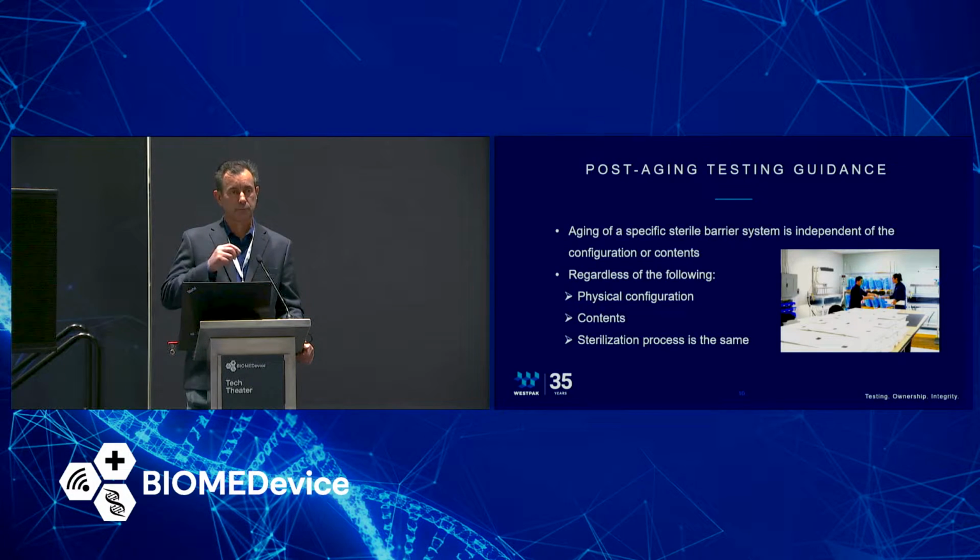And the aging, if we're looking at just the packaging, again, the sterile barrier system, the aging of a specific SBS is independent of the configuration or contents. So in a sense, you can put anything in your package if you're only looking at the packaging, and that's my point. So it's regardless of the physical configuration, the contents that's in there. However, it does have to be subjected to the sterilization process. That has to be the same because sterilization is going to stress the packaging components.